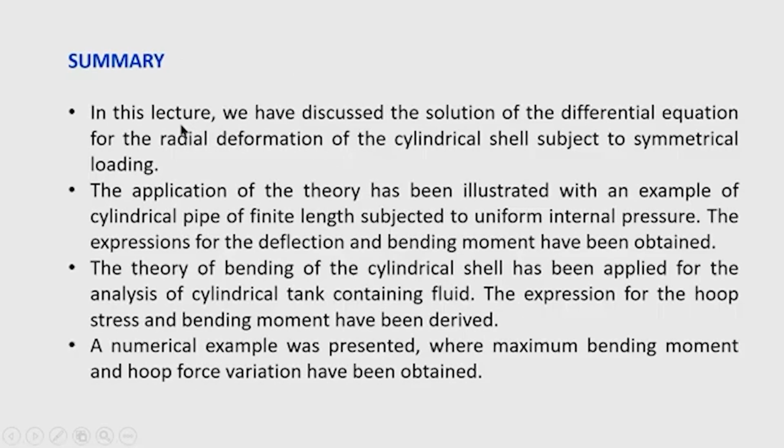Let us summarize today's lecture. In this lecture, we have discussed the solution of the differential equation for the radial deformation of the cylindrical shell subjected to symmetrical loading. The application of the theory has been illustrated with an example of a cylindrical pipe of finite length subjected to internal pressure. The theory of bending of cylindrical shell has been further applied for the analysis of a cylindrical tank containing fluid. Lastly, I have given a numerical example to illustrate the theory. Thank you very much.